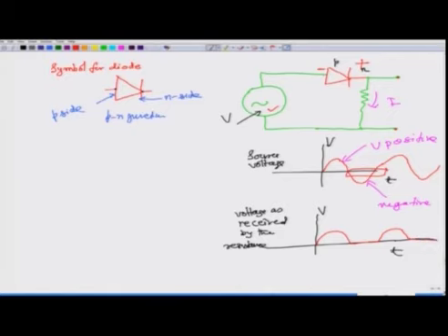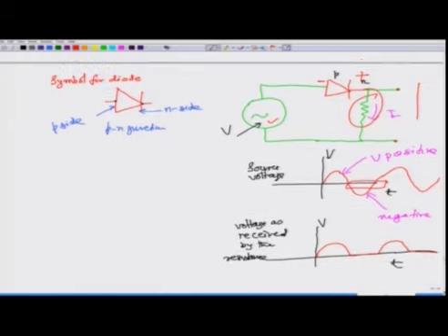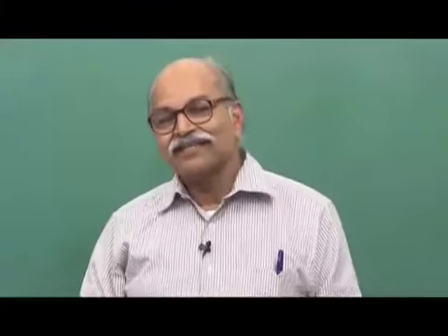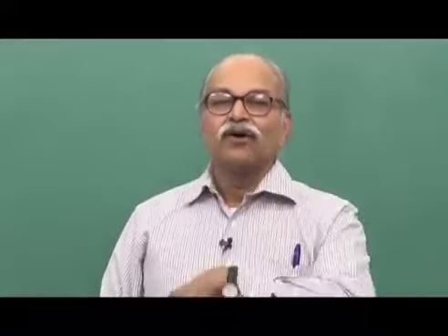So, what has happened? In this resistance, the current is either in this direction or it is 0. So, at least the direction part has been taken care of. It is not a very good DC. A very good DC means you should have a constant voltage like a battery. So, this is certainly a very bad DC, but it is DC in the sense that the current is not reversing direction; either it is going in one direction or it becomes 0.